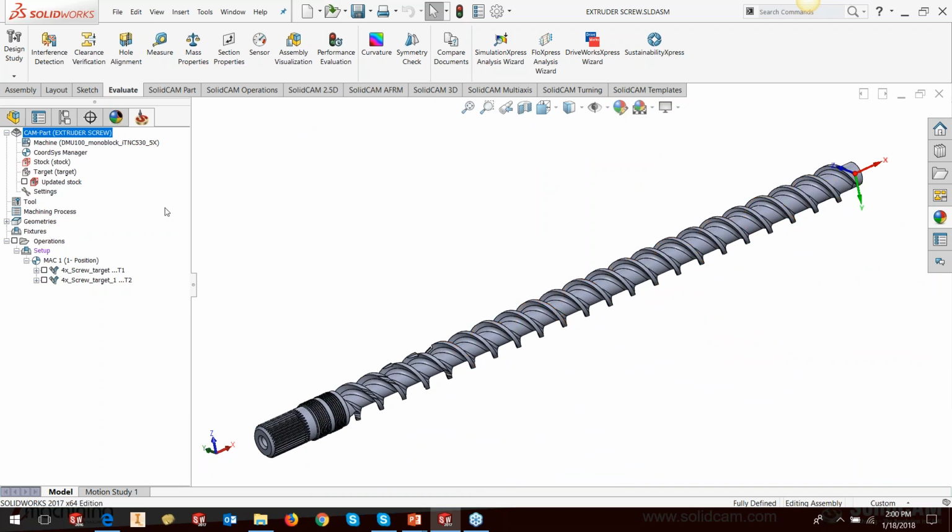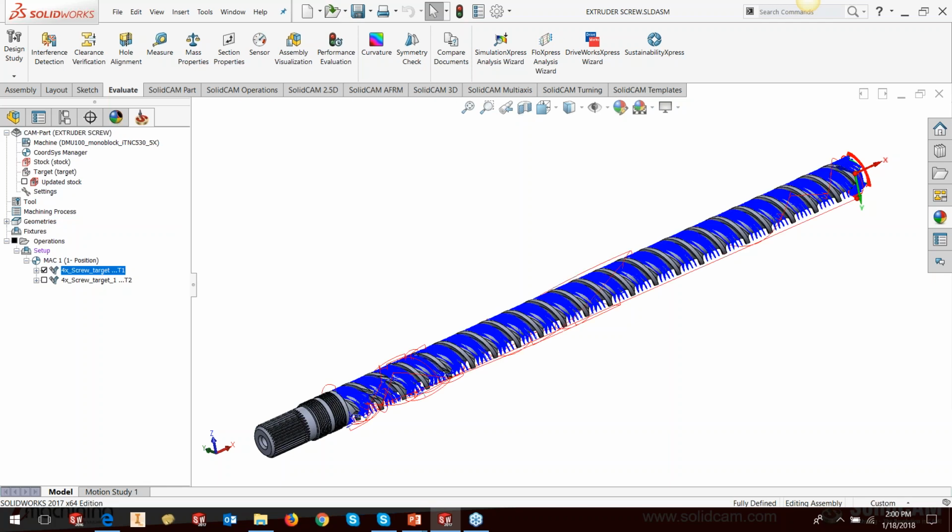Again, what we did, simply selected the part, selected the stock, the tool, depth of cut, side step, and rotation direction, and I get the tool path. This part took about 15 minutes to calculate, but then 15 minutes, I would say, for such parts, compared with manual way of working, which would have taken a day at least, 15 minutes is lightning fast. Okay, it's very fast. You don't have to worry, it's machining every feature in it.